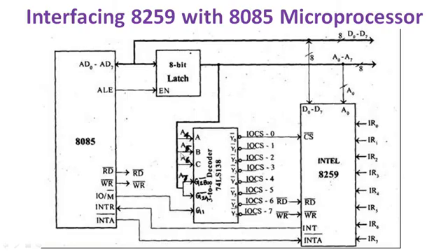000 bit pattern arrives on CBA lines of decoder, that time the Y0 line will go low and all other lines will become high. Then this A7 line is given to G2A bar and G2B bar, these two lines. Here G2A bar and G2B bar lines are active low lines. So A7 line should also be made low to enable the decoder, and G1 line is active high line. So this must be 1 to enable this decoder. So here IO/M bar pin is directly connected to G1. That means it is IO mapped IO.